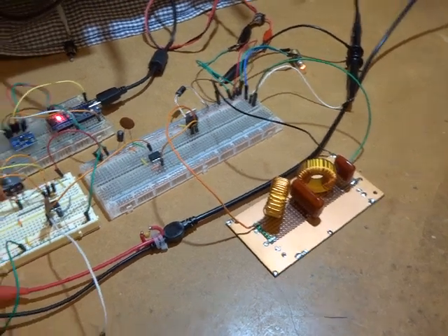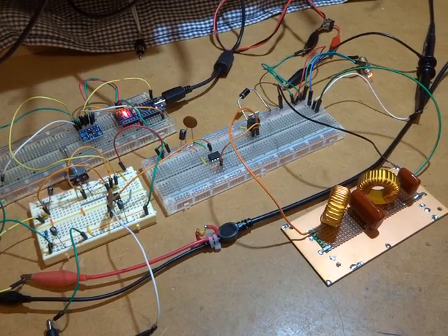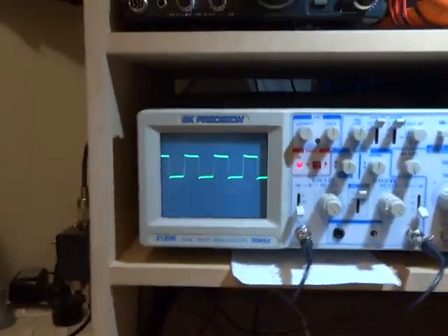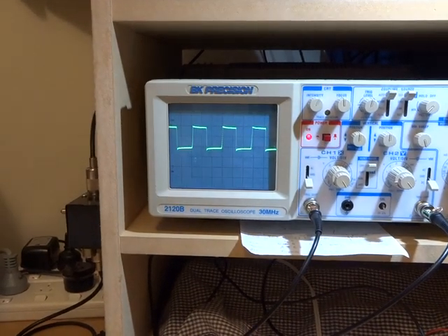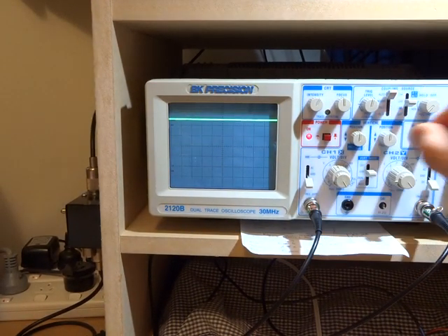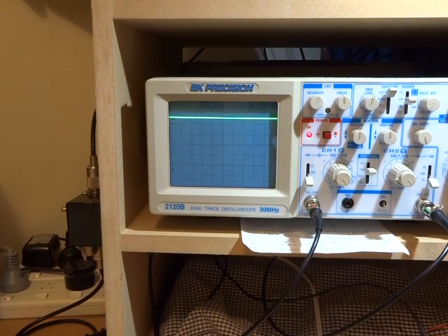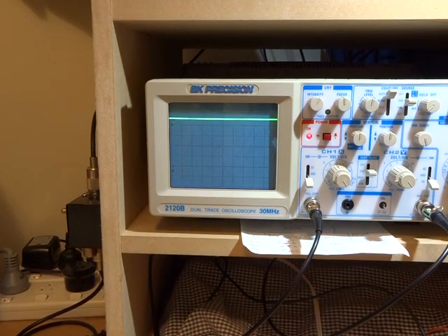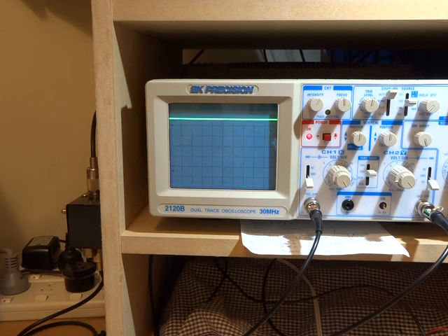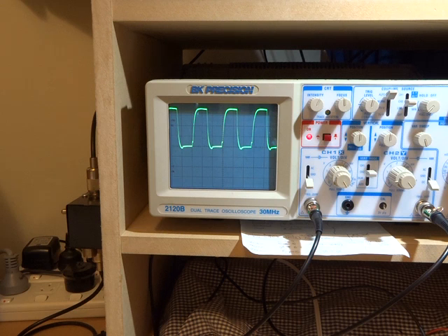Right, so what I will do is just have a quick look, back on the scope, at the output of that low pass filter. If we go back to our other channel, that varying waveform you can see there is the output of that low pass filter. If I remove the earth that's been provided to that particular little board there, the filter is no longer filtering, and as you can see there, that's essentially the input.